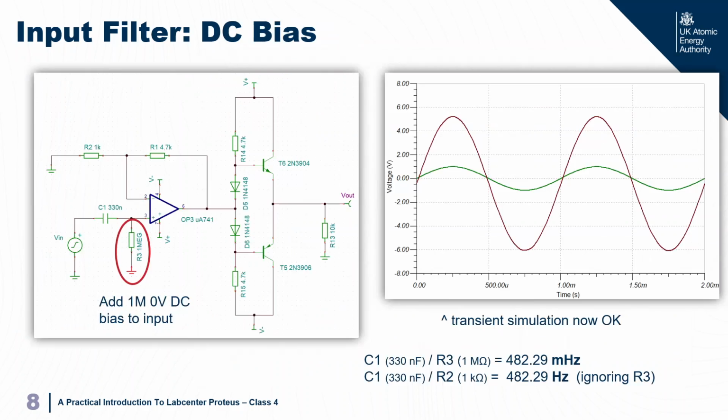No, it's nothing to do with 1 meg. The only reason why you can kind of ignore that 1 meg is because this capacitor can share current with that 1 meg resistor. It can't share current with that 1K because there's no current in and out of these points, even though the op-amp holds these points at the same voltage. Except it's negligible if there's any. Yeah, when I say no, I mean it's very, very small. Gotcha.